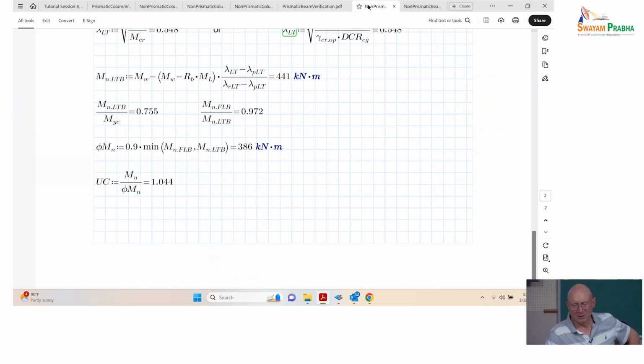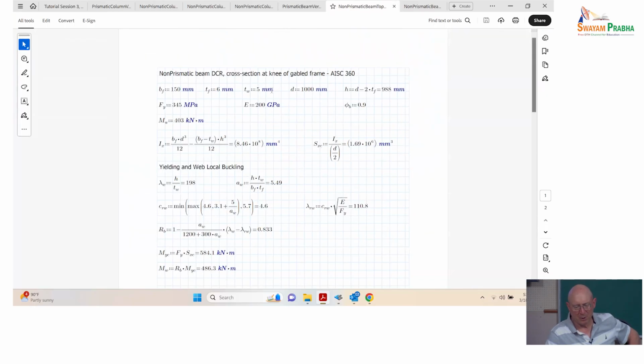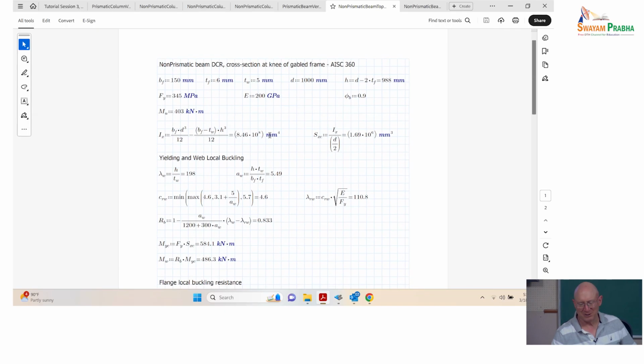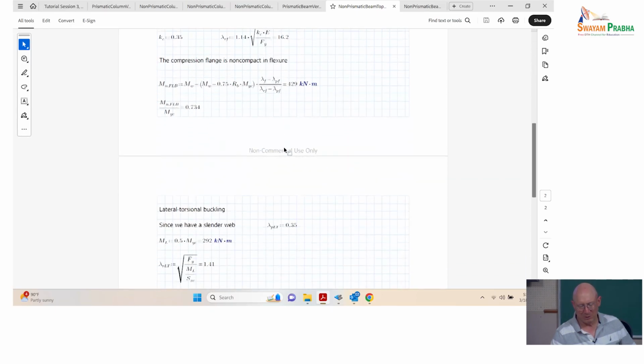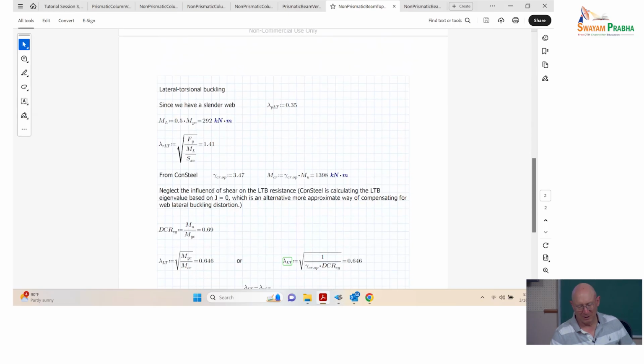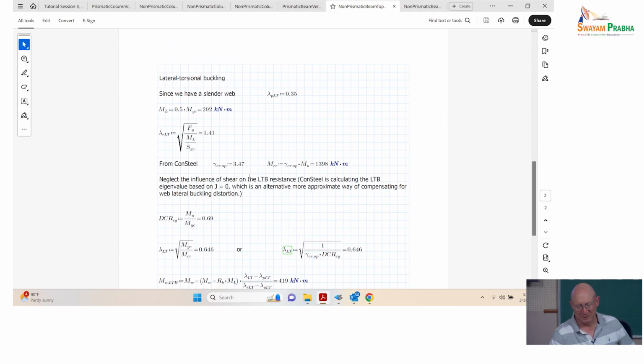All right, so let's suppose that we figure the top is the most critical. So it's the same cross section we were just working with, the prismatic member I just showed you. So this file is largely the same, except when we get down here to gamma critical for out of plane, it's 3.47 now.